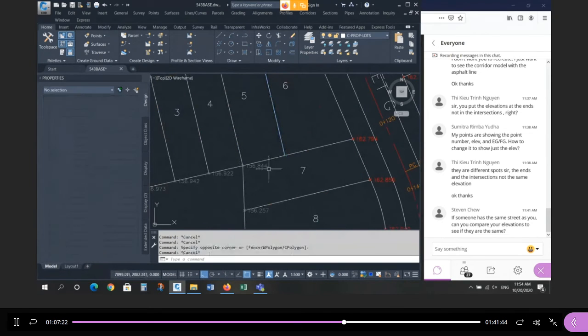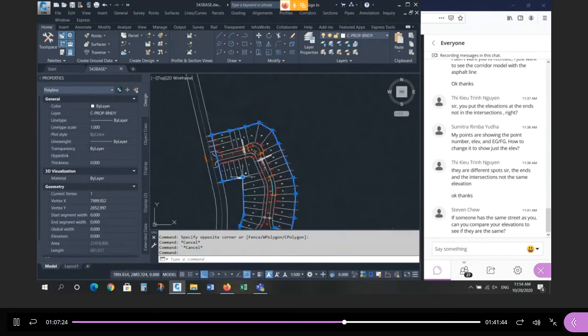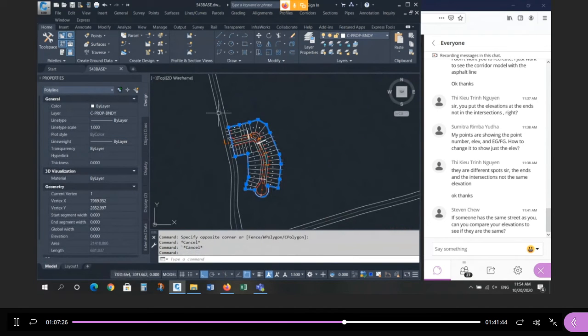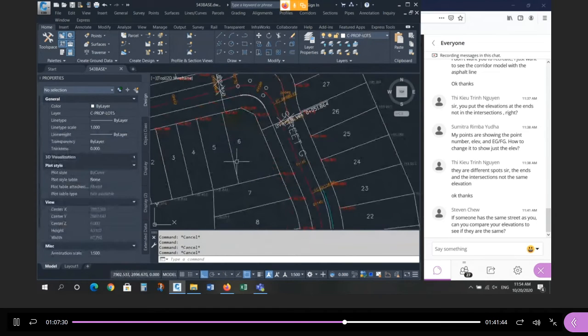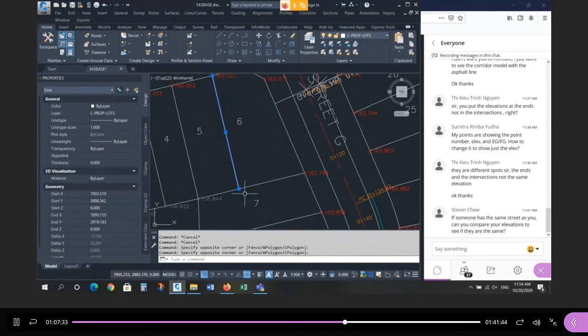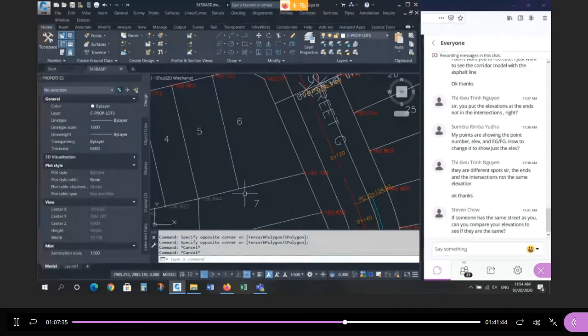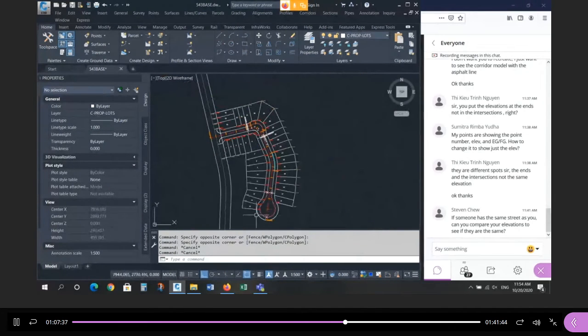In here, don't do anything. Only on the perimeter of the site. Only on the perimeter of the site do you need elevations, and only at the front street line do you need elevations. Internal, what to do here? That's assignment 4. So don't get lost there. Just the perimeter, the outside of the subdivision and the edge of the street inside the subdivision. Those are the only things you need to concern yourself right now.